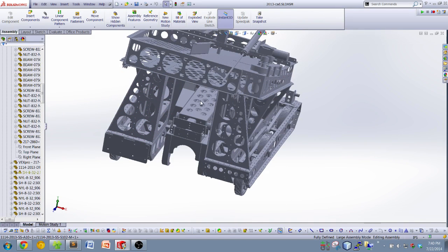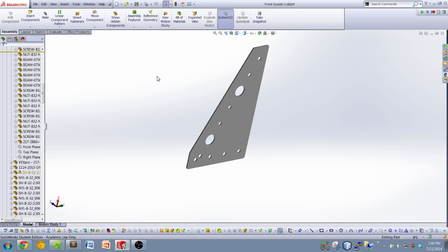Can you move those parts around? Because when they release them as STEP files, which is a format that any CAD package can open, like Inventor can open it, everybody can, it loses those properties. It actually loses all of the mates. So it keeps position, but it doesn't have any mates. So normally when you import somebody's robot, you end up just fixing everything and not moving it around. When you build your own and you build it all in SolidWorks, you can do things which I can go through. Let me pull up, let me see.